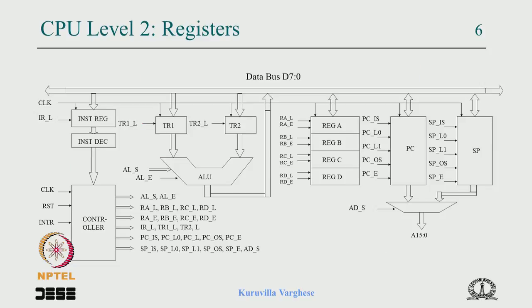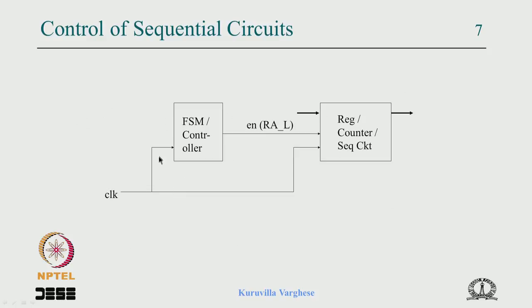And we have also seen how the state machine generates some enable signal. In particular we looked at the register, and how this latch signal enables latching the data from the input side. We have a register and an FSM working on the same clock, and this latch signal is decoded from a state which is controlling the register.